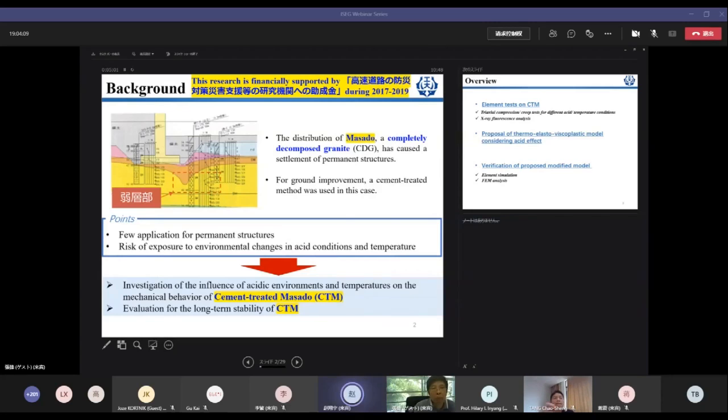And on the other hand, I proposed cement-treated soil, which doesn't use any pile, but uses the cement treatment method to enhance the weak layers beneath the foundations. So this is quite cheaper, only one third or 1/4 of what should be spent for micropile foundation. And then the 2 proposals were accepted.